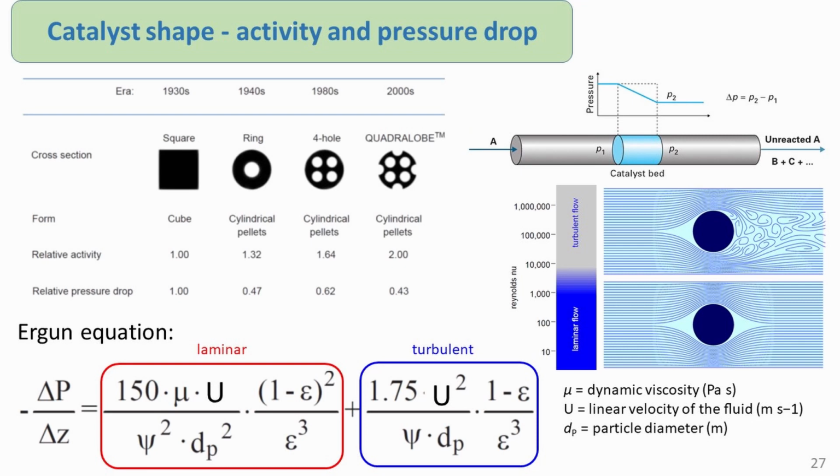The space velocity has conventionally been used to determine the necessary catalyst volume for a given amount of feed, but this parameter gives no information about pressure drop, heat transfer, or risk of unwanted side reactions. So advanced models are necessary to evaluate the design. The catalyst must also ensure equal distribution of flow between tubes in a tubular reformer and across the catalyst bed in adiabatic reforming. Maldistribution may cause local overheating or channeling and hence a shorter lifetime of the reactor. It means that the pressure drop should be carefully monitored during the catalyst loading.